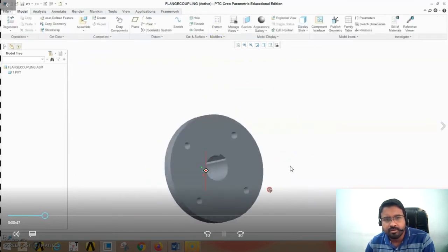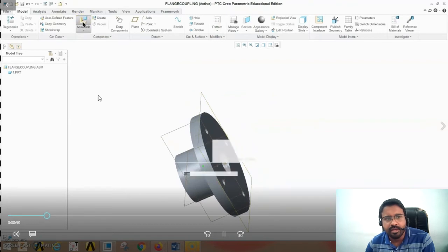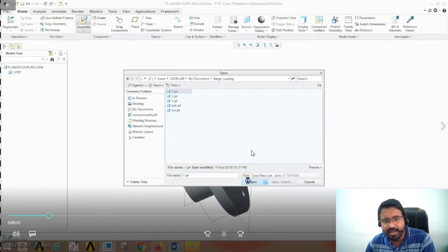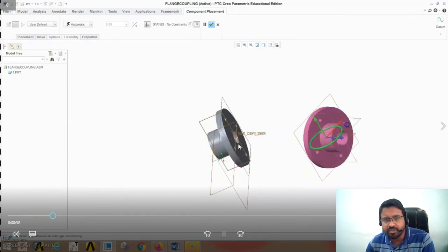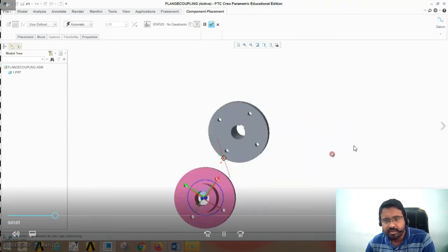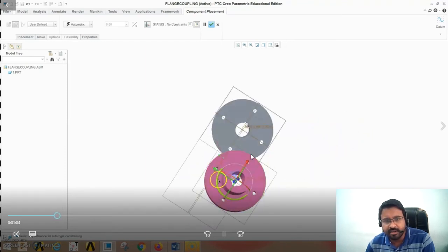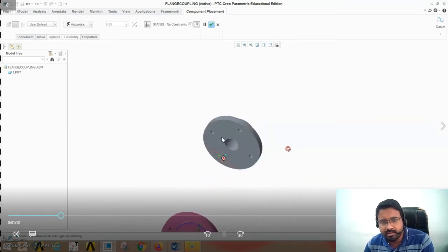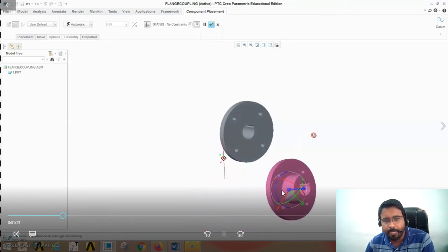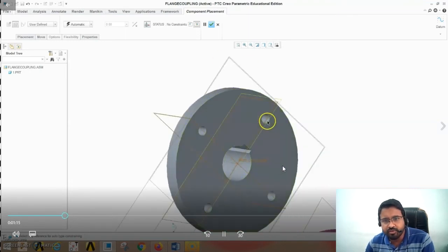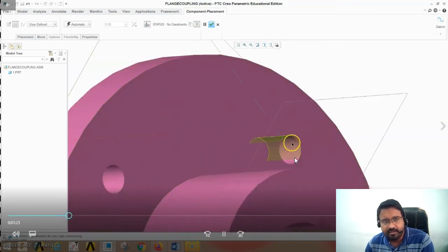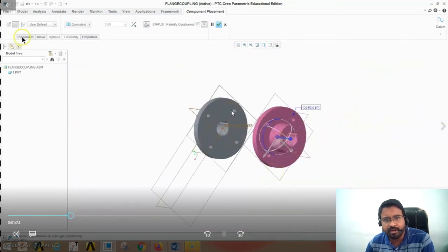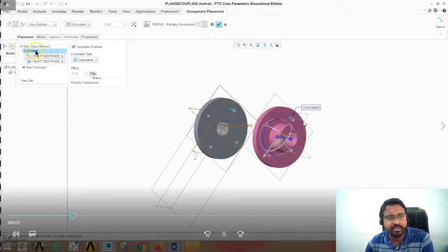So accept here. Now again you go to assembly and take this part again, because you need the two flanges on opposite sides. So you can rotate it and match it to this axis. Now we have to constrain it so that it fits in. We manually rotate. See that. Now to constrain it, we choose coincidence automatic from here to here. One hole to another hole coincidence.